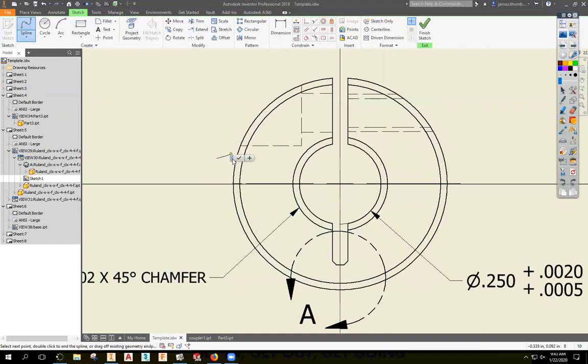And so now I'm just going to go here. Make some kind of squiggly line, and then circle back around and reconnect it. Because I clicked on that first point again, it closed it and made it green. Okay? I don't need to constrain this or dimension it at all, because the size where those lines are doesn't matter. I just want an enclosed area where I'm going to do my broken out section. So I get that, I hit finish.